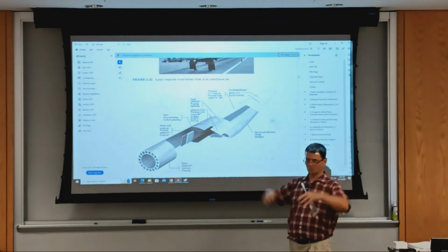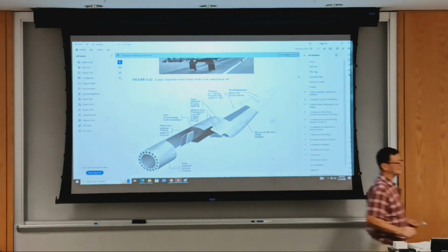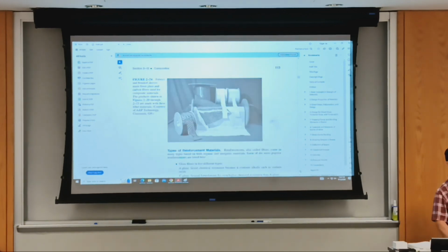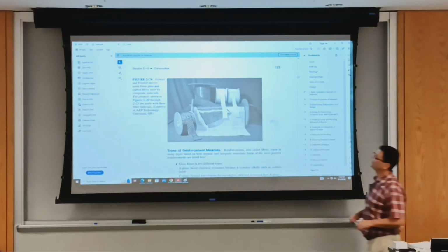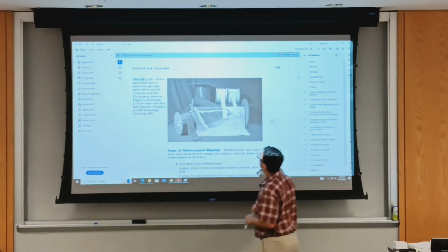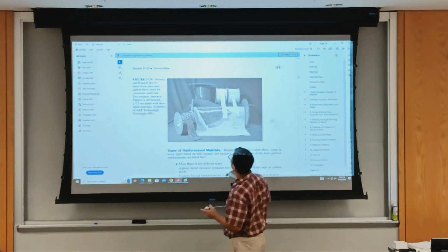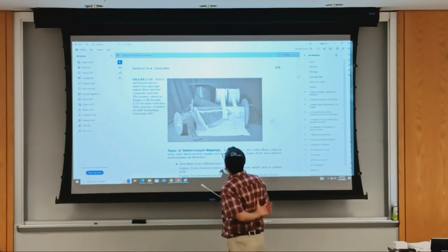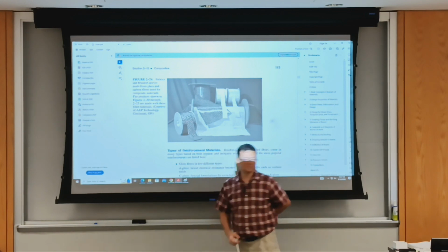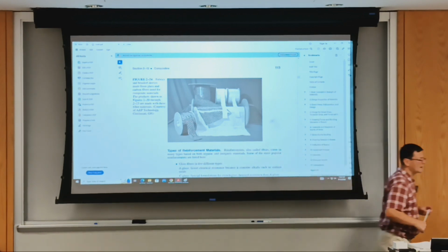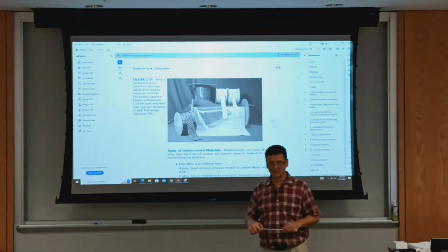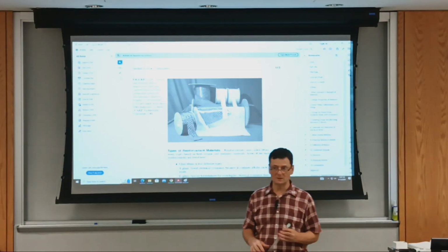They're formed over a mold. They use what are called pre-pregs. That is, they present themselves like these. They're pre-impregnated fibers. Could be glass fiber, and the size of the fiber and orientation matter. It could be mesh. And then you have what? Carbon fiber. Carbon fibers are just nylon fibers that are baked until they turn into carbon.